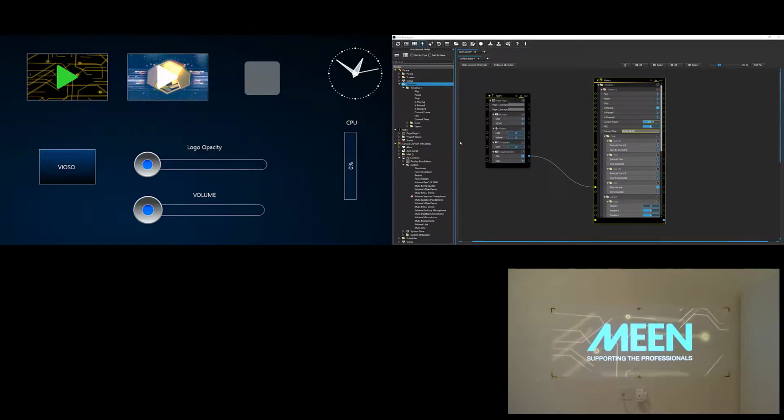Now we want to even have control over the stop button, because now it's playing back in a loop. So we go to stop from the stop button output to the stop functionality of the Pixera timeline. Direct connection again. So once we press the stop button, the show stops.